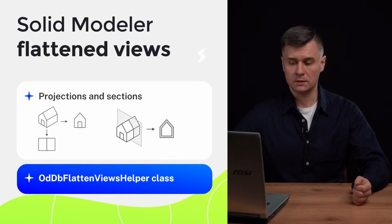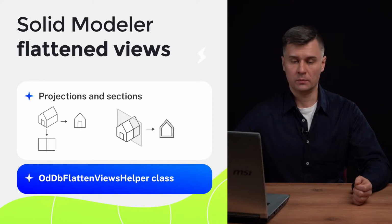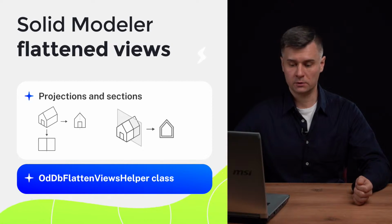The extended tool has a method to copy the result of projection or section creation to the selected block. ODB Flatten Views helper is a part of API to support DWG format, so it cannot be used out of the ODB API. But in future, we are going to separate precise hidden line remover to a new model independent from ODB and provide our own PHLR API. In that case, precise hidden line remover also can be used. It will be possible to use it out of the ODB scope.